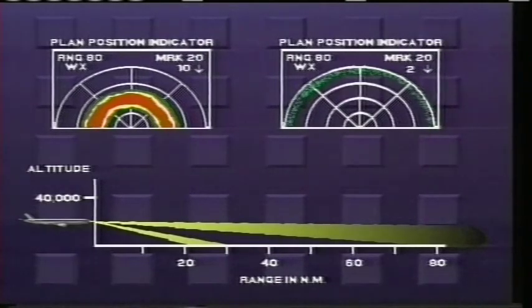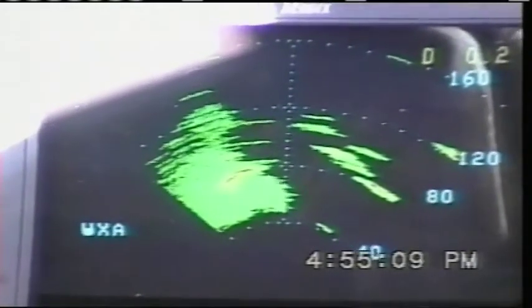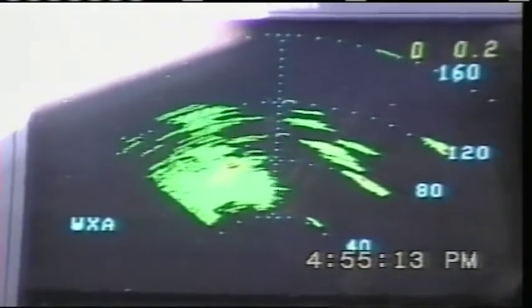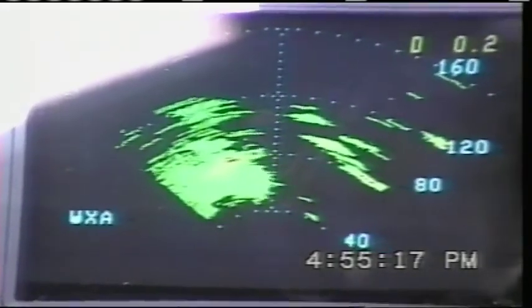As the climb proceeds, continue to make small adjustments to the tilt as necessary, until the aircraft reaches the cruise altitude. This procedure will correctly point the antenna beam and create a zone where no storms can go undetected by the radar. Some pilots prefer to use the 160 nautical mile range at cruise altitude. If that is your preference, switch the radar to that range and repeat the tilt management procedure.